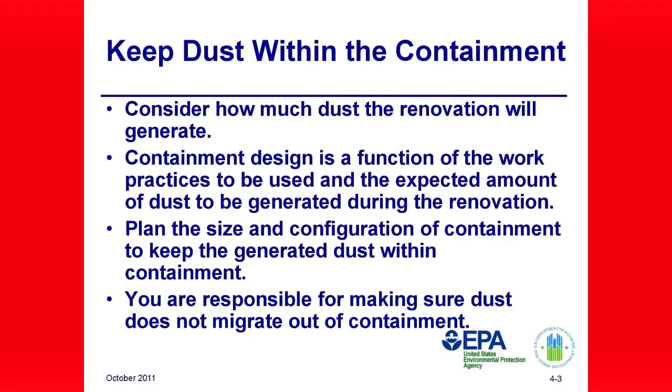In general, renovations that involve only a small amount of paint disturbance create less dust than jobs that involve large areas of paint disturbance. However, in addition to the size of the area of paint disturbed, the work practices and equipment used will also affect how much dust is being created and how the dust will be migrating. The location of the work activity also has a bearing on the amount of dust that is being disturbed. For example, small areas of ceiling work can spread dust over the entire room and are very difficult to control.